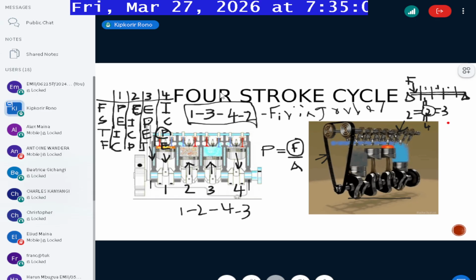Now, in modern vehicles, we have distributorless systems, so the ignition timing is controlled directly by the ECU, the electronic control module. The ECU simply determines at what point the firing occurs, according to the firing order. Also, in modern vehicles the valves are not completely controlled by the camshafts. For example, in VVTi systems in Toyota or the i-VTEC systems in Honda, we have variable valve timing with intelligence. So you have the ECU also controlling the timing of opening and closing of the valves.